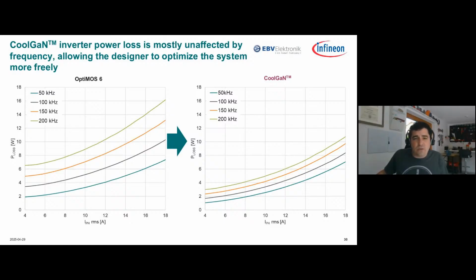With GaN, you kind of flip this logic on its head. The penalty is so low, it's basically negligible. So then the question is, why not go to higher frequency? There's really nothing holding you back. We can switch very easily at 100 or 200 kilohertz, and the full load power loss, the system efficiency is still lower than silicon would be at low frequency.